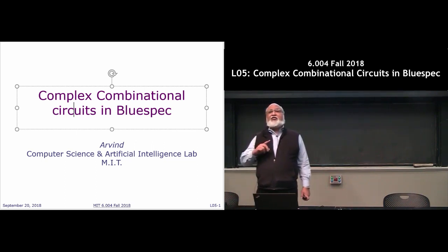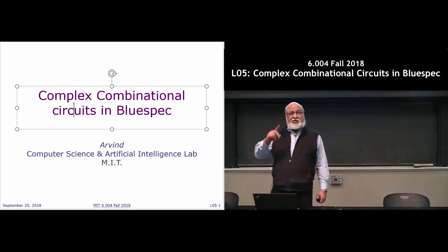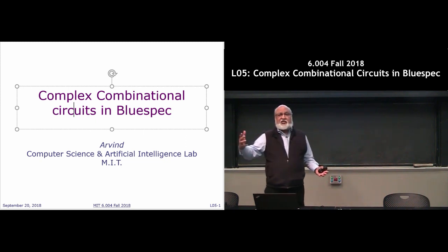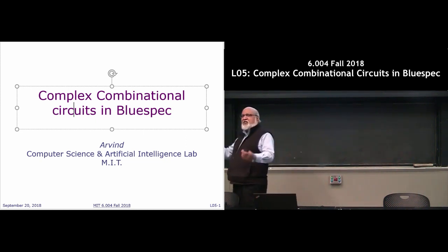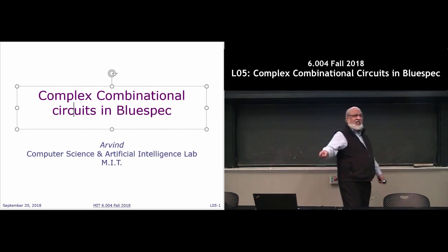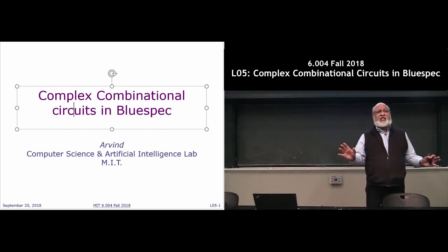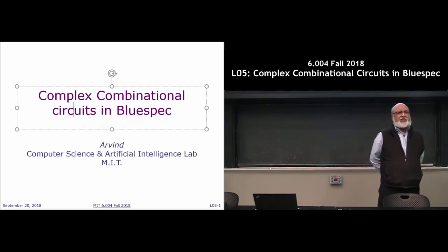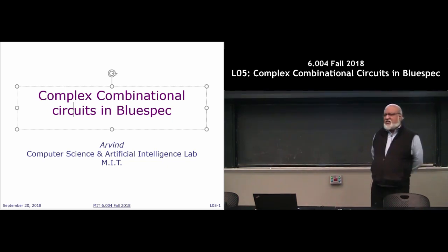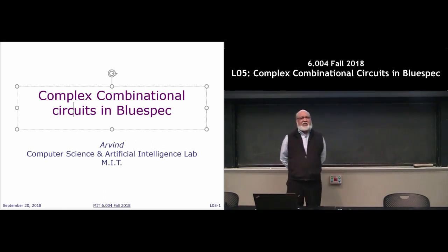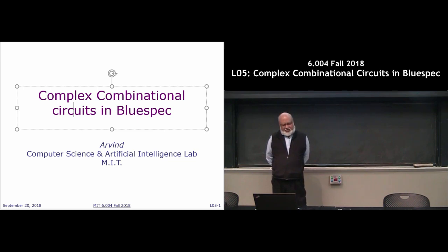Set of all functions which map integers to integers. Right? So mathematically, there is a set which may be tremendously large, I don't care. But you have constrained it. If you are expecting a function of this type and somebody tries to feed it a Boolean, it will immediately say, sorry, you have violated the types. So when I say things have types, everything in Bluespec is going to have a type. Functions have types, modules have types, everything is going to have types.